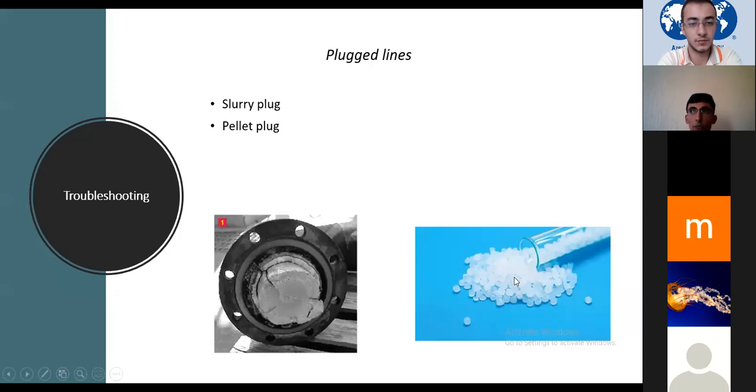So in order to transfer powder, we use nitrogen blowers. In order to transfer pellets, we use air blowers. Why nitrogen? Because after the dryer, we still have a probability of some hydrocarbon together with our powder, so we don't want those hydrocarbons to meet oxygen yet. So we use nitrogen blowers. But after extrusion, of course, we don't have any hydrocarbons inside, so we use air blowers to transfer the pellets.